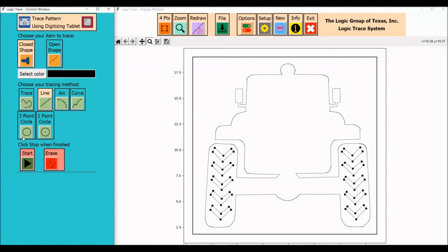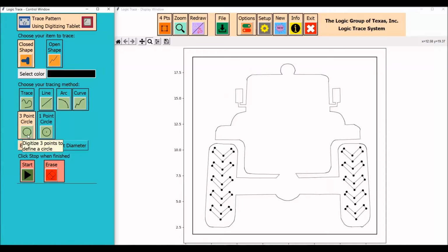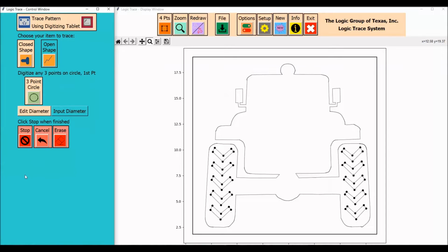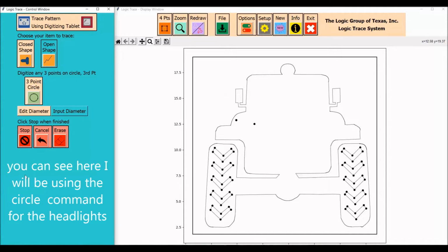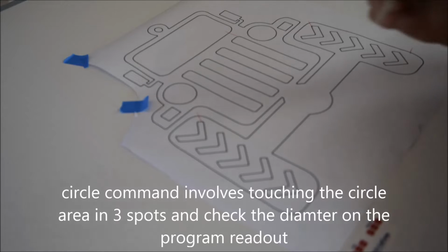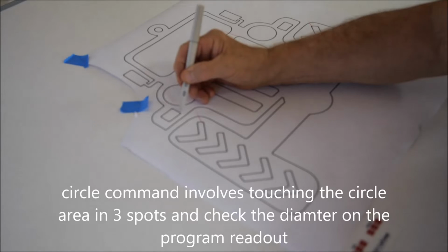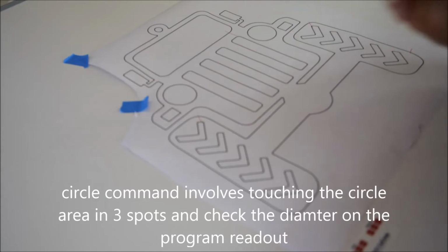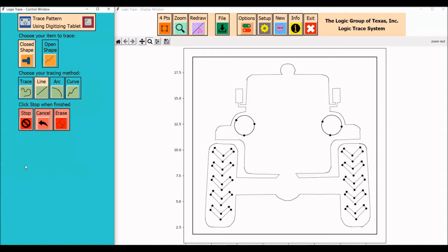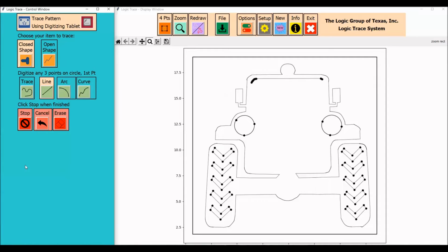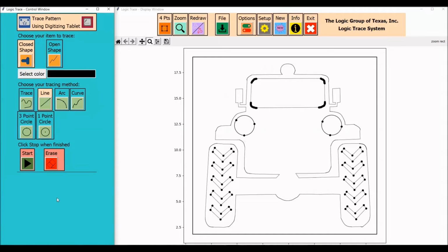The difference is I'm using stainless steel or cold steel, and I'm using oxygen assist as compared to air assist. Cutting of the metal is all new to me, so I'm just in the learning stages, and that's why I've done about 3 attempts here to see the differences in the cut. And it looks like the stainless steel is the best cut because the cold steel and the galvanized metal, which is tin, they're rough on the backside.